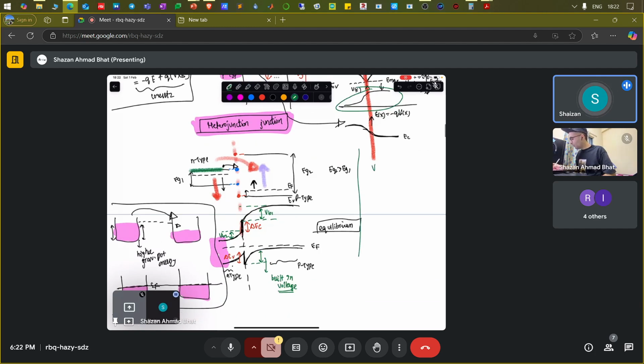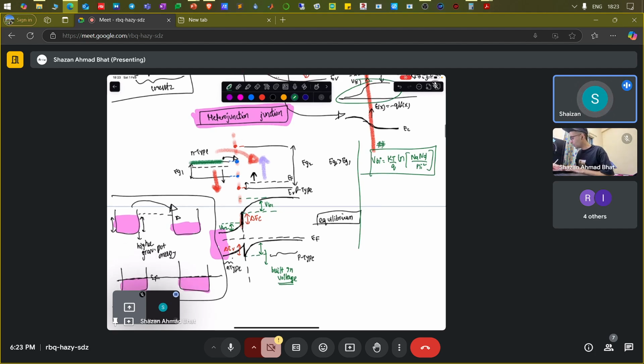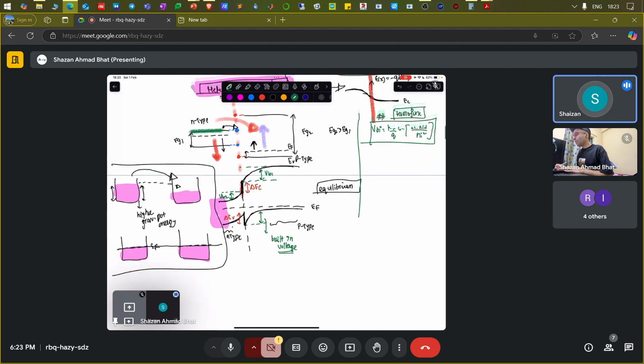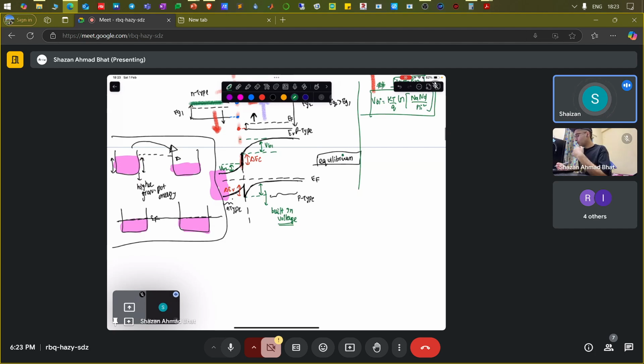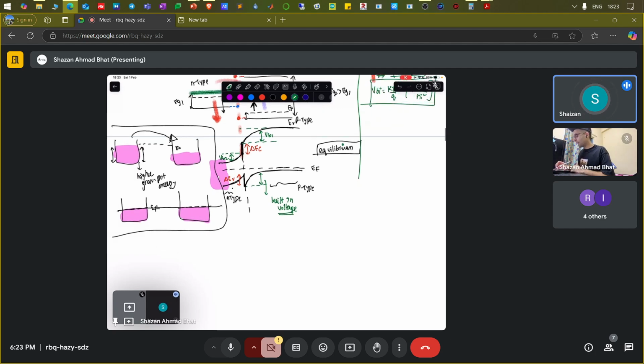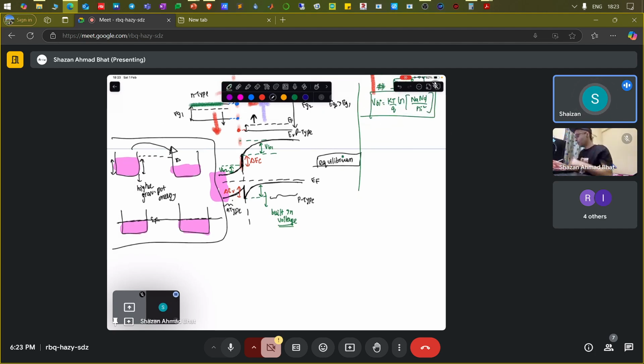And the built-in voltage in a homojunction, you knew from basic device physics, we used to compute using Na Nd divided by ni square. This was the relation which you computed using Poisson's equation, if you remember, in the homojunction type of device. But here you don't have any doping, so you don't have an acceptor-type or donor-type impurity here. So different rules are followed in order to obtain the built-in potentials. That is one of the problems in your assignment section.